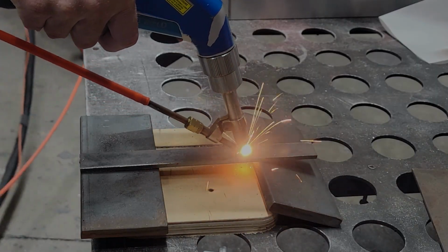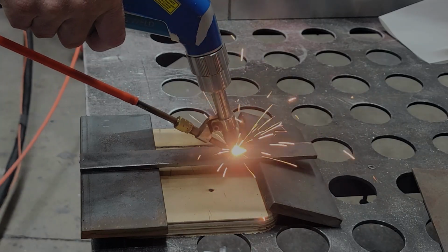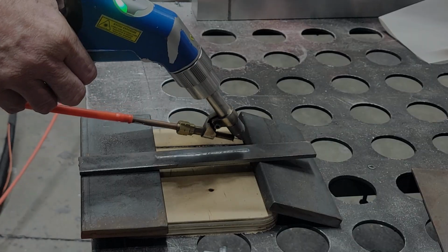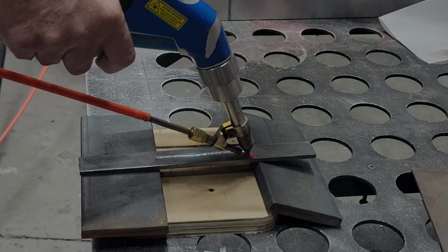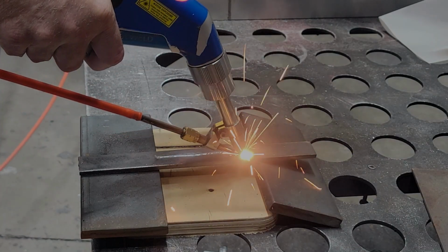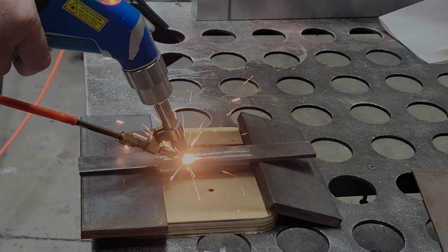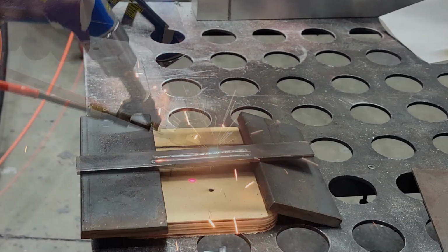Why max penetration fails at high speed. Energy per unit length drops. As speed increases, the joules delivered per millimeter decrease. Keyhole instability: the molten pool doesn't have time to stabilize, so penetration depth collapses.